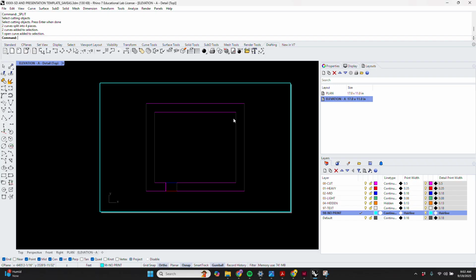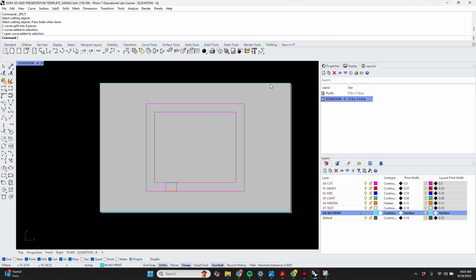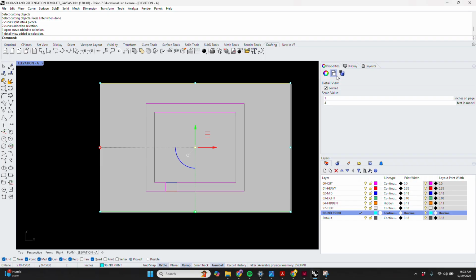But so we now want to align this with the next reference down in our model space. How do we do that? So we're back to paper space where we have that detail view by double clicking, or like paper world with the gray. We click on that, properties, and so remember this is locked, so we can't change what is shown here.